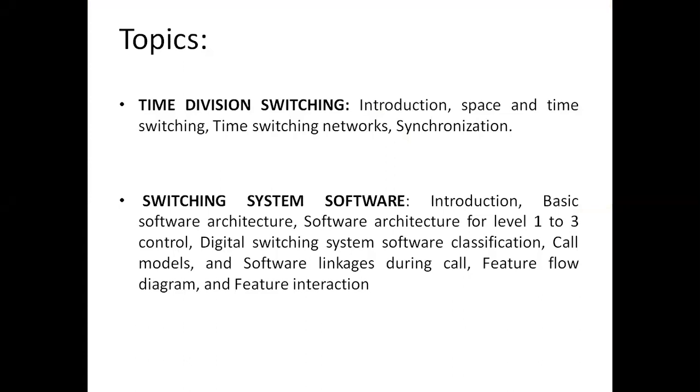In the first part, we discuss the different switches: time switches, space switches, and a combination of these, where we form time-space-time switches and space-time-space switches. We also discuss the grade of service of these switching systems, and the synchronization network.